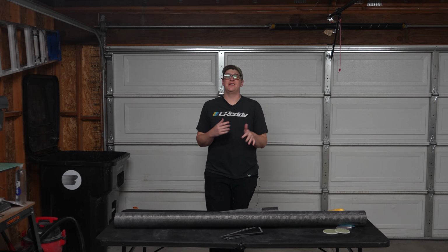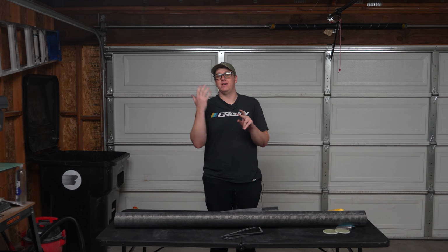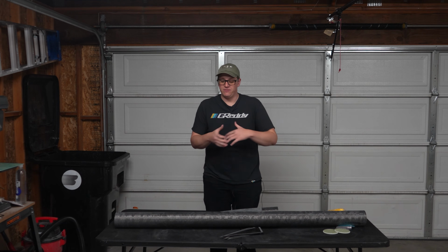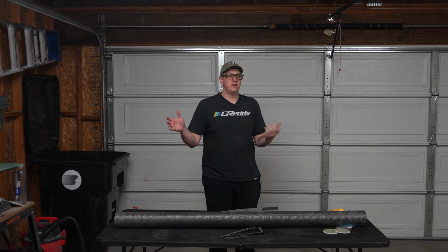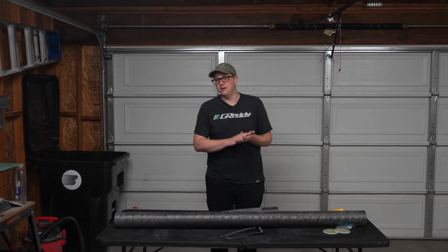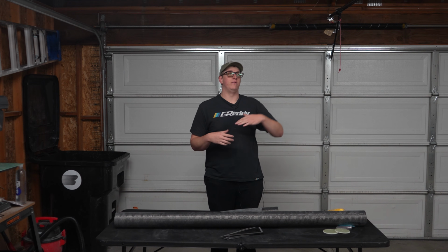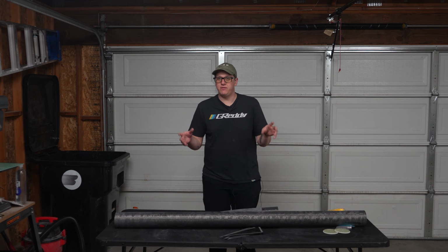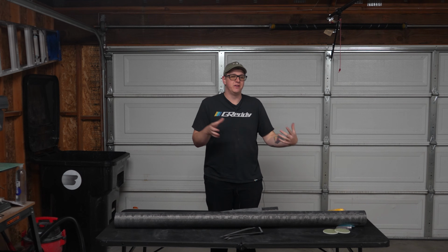Make sure your sim files, especially your fin shape and dimensions and your weight and center of gravity, are correct. This is the ultimate way to ensure that you have proper safety for loading a motor. If you don't have the motor on hand to put in the rocket immediately and check the center of gravity, you can get a very good idea of whether or not that motor is going to need nose weight, or how high it's going to go, or if it's going to take off too slow because your rocket weighs too much. This is all very, very important stuff that brings a simulation into a field of necessity.